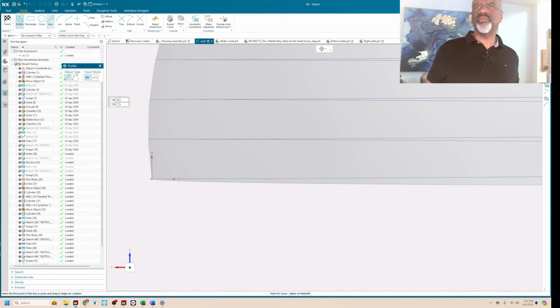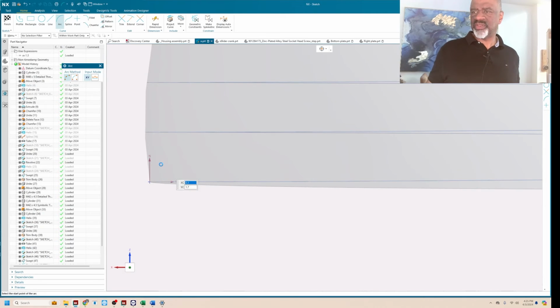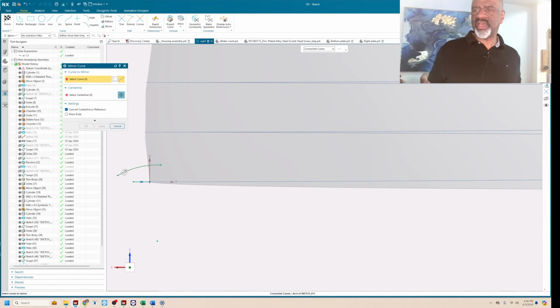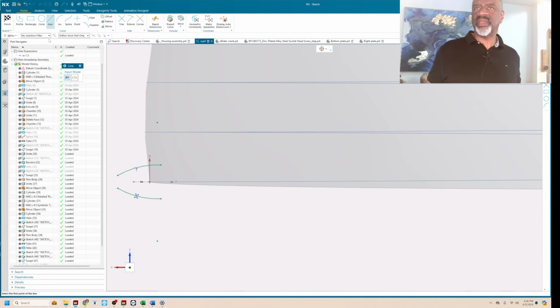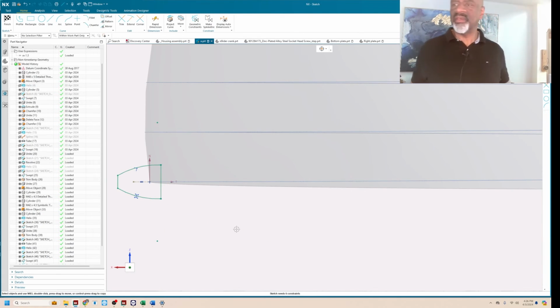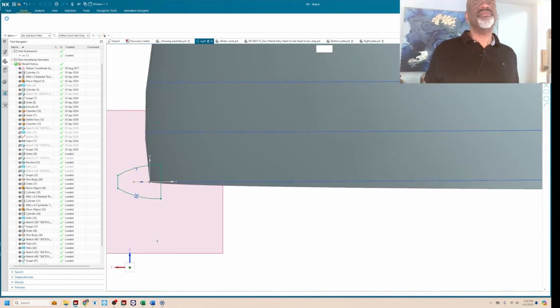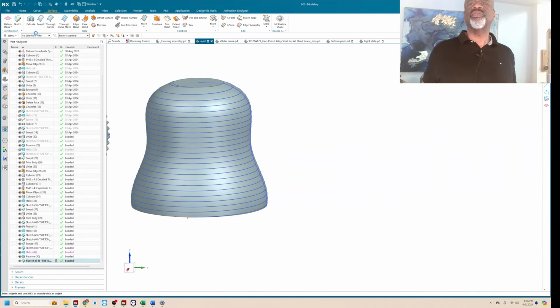I think this one will be a little bit more interesting. I'm going to start with an arc that looks like that. I'm going to put a little line segment that emanates from that little center line there. I'm going to go to the mirror command, where I will mirror that arc around that little doodad right there. I'm going to then just close it off with some lines. There's one there. There's one there. And there is my tooth profile. Beautimus.